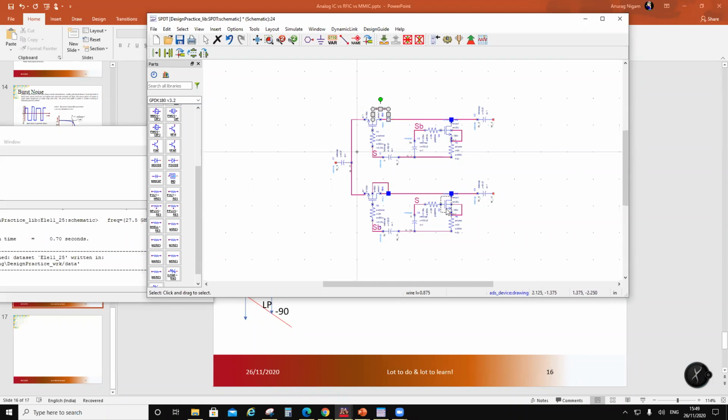Okay, so here I have made a mistake. So you are correct. So you are saying that it should go to the source. So there was a mistake in connecting this. Okay, this should be connected over here, and this should be connected over here. Okay, thanks a lot. So I understood what you mean by that. Yes, the body connection has to be to the source. So that's fine. And the source has to be at a known potential. So that's why the source is always on the input side. Okay, so thanks, Nazif. So I made a mistake there.